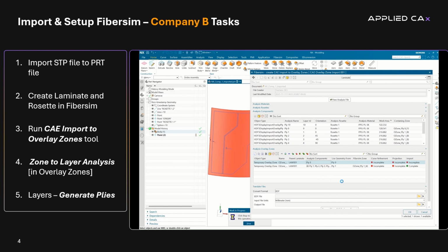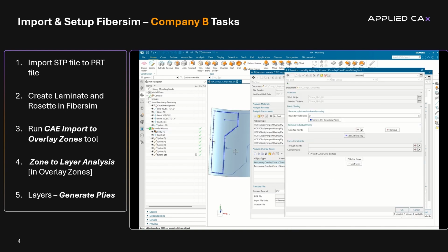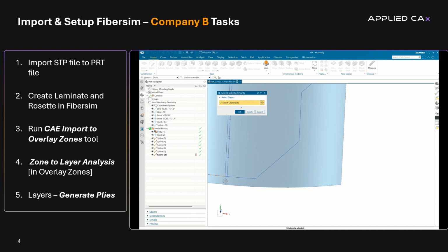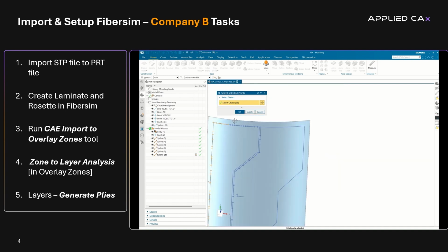Sometimes with the HDF5 files, you have a bunch of points and it's creating curves directly over the net and extended boundaries, and sometimes it'll result in an invalid boundary. And so we're just going to remove those points.